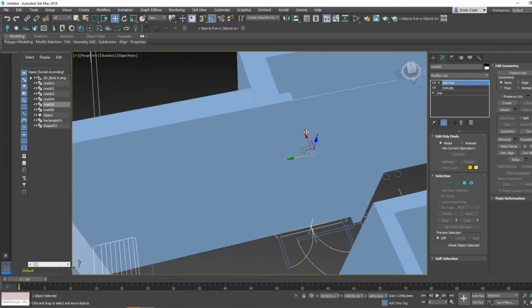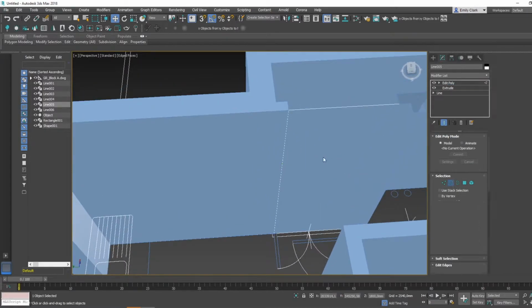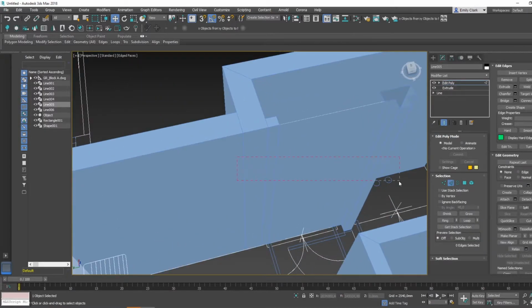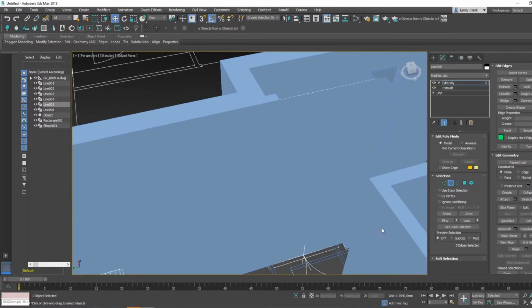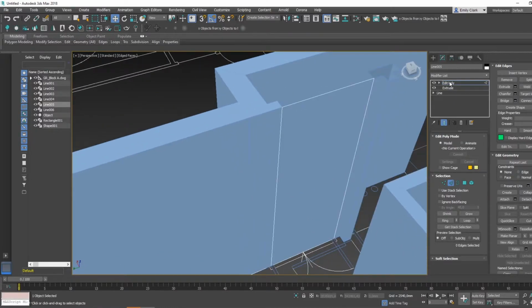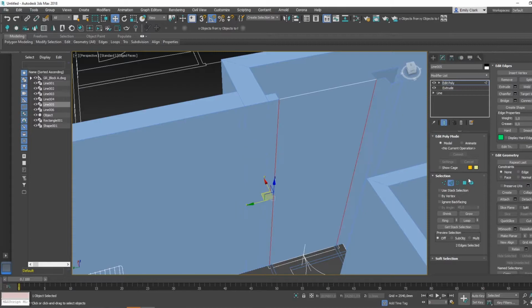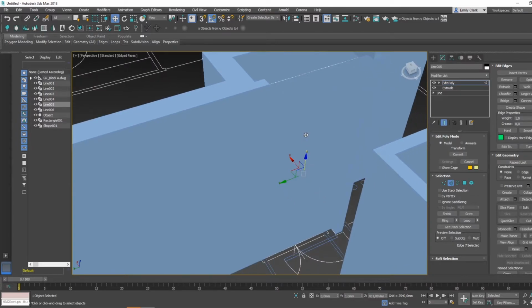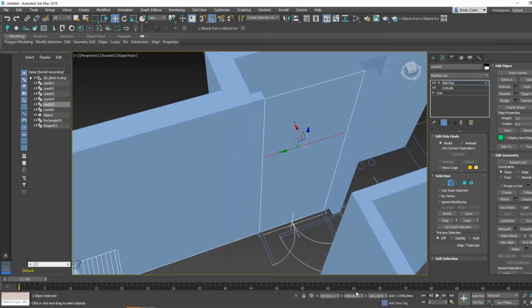And then this door, so the standard height that we use is 2145 or 2345. Alright, so we've extruded this and put an editable poly. So with my lines, I'll just ring this, connect with one, and bring this connect line up to 2145.